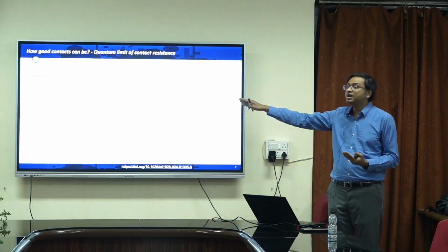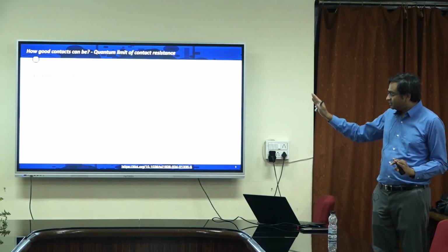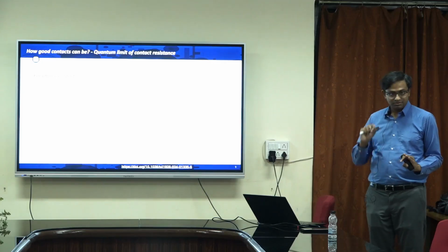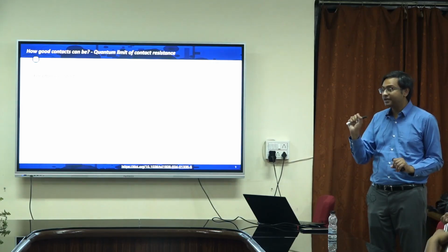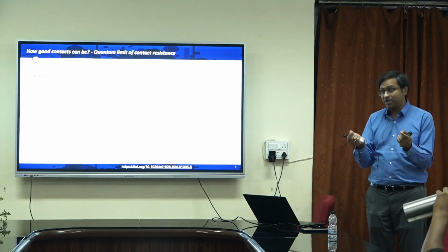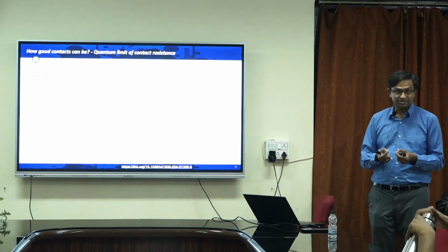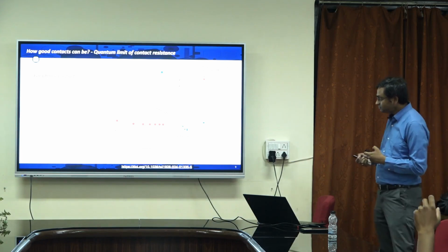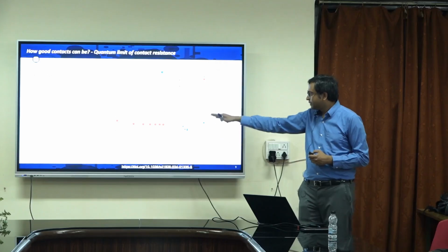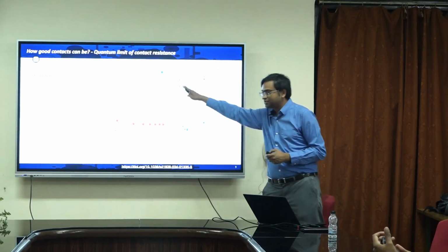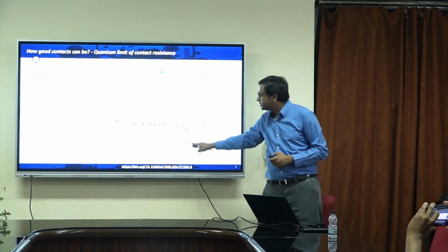And you see that you want to have a very large N2D. Make sense? That is the only way to reduce contact resistance. Higher carrier concentration, which means I am targeting really degenerate doping of the channel underneath the contact to reduce the contact resistance, right? So here is a plot. You see that as N2D increases, this is the line. Forget about these, these are all experimental results, we will talk about later, but this is the formula for the RC0, correct.